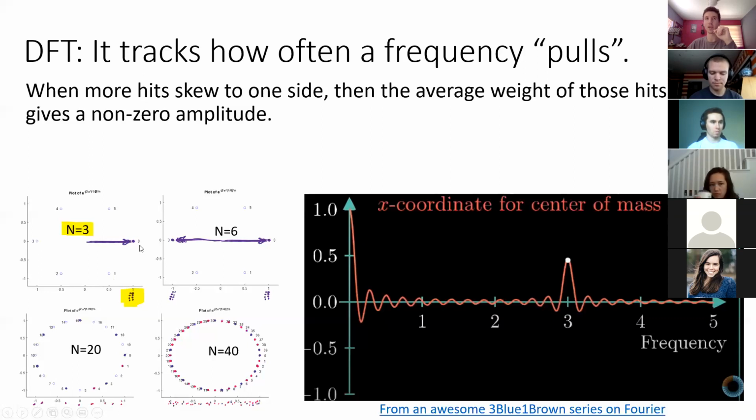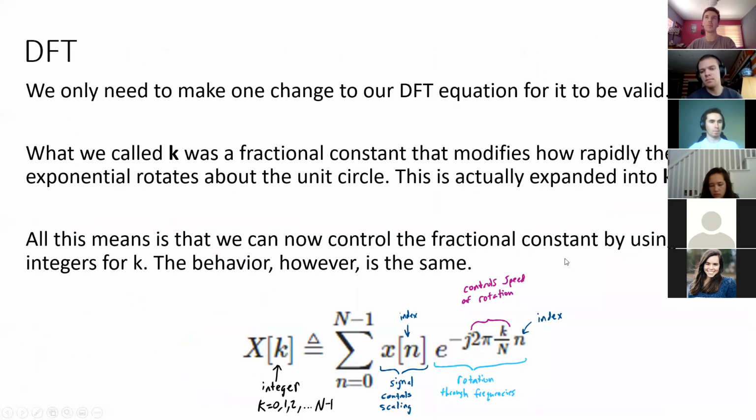And then you keep on winding up back at the same point. So all your dots are going to be concentrated. And so if you look at what the weighting is of this over frequency, over this n value as you change it, you're going to see that some of these values cause more weighting than others. And so in this case, we get a positive value of the weight. It actually evaluates to 0 here. This also evaluates to 0. So most of these terms will evaluate to 0. And then at the points where the frequency is in that, you'll get some non-zero term, and that's your peak.